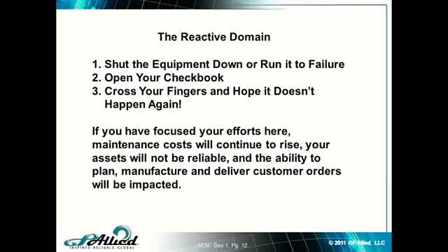Go back the other way on that PF curve. Focus your efforts up front. Start with design. Use those tools. Use the experience of your people to understand the failure modes and design these things out, right? Once we understand, again, the failure modes, what's the correct maintenance, and then do a great job of installation, and we should have a nice, long IP interval.